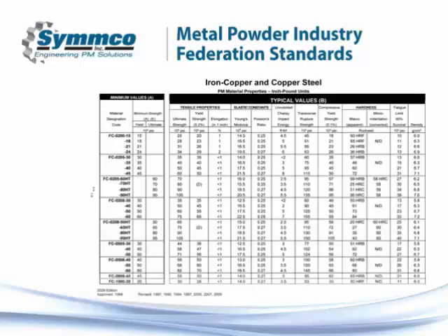It also creates a couple different methods by which we can confirm strength: transverse rupture strength, yield strength, tensile strength, and compressive yields. So there are ways to identify the material is compliant to the needs of the engineer. It is complex, though. There are many, many materials, and we just briefly talked about oil quench and sinter hardening.